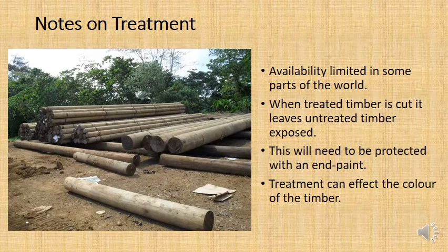So a couple of notes on treatment of wood. I will say that treated timber is so common. Really, nearly all timber, especially if it's being used in building in any sort of capacity, should be treated to some degree chemically. Well, this is a difficult thing for availability in some parts of the world. Kurdistan doesn't have a lot of trees, and it certainly doesn't have any chemical treatment facilities at timber mills.